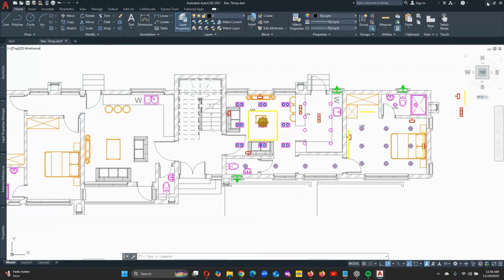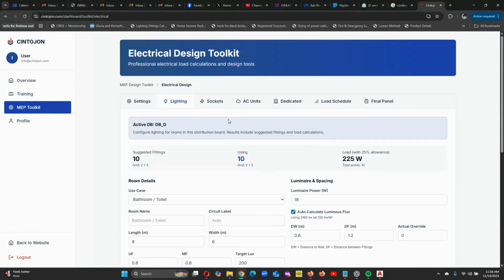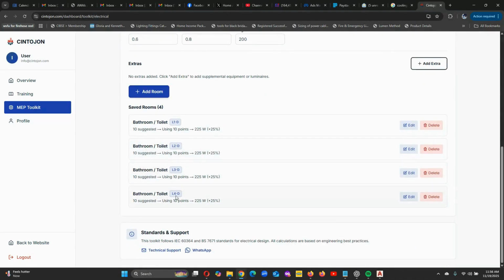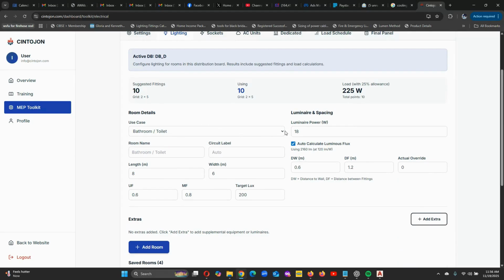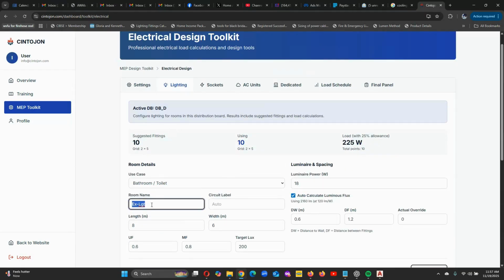So that one, I don't even need to bother myself, all right? It depends. Let's say I want to put it on a single phase DB with all the other street lights or whatever it is I want to do. I want to put it on the same circuit. Say, okay, this L4D. So I can just put that on L5D. So I can just call it EXLGT. Okay, external light. Let me put it in caps. It doesn't matter really.